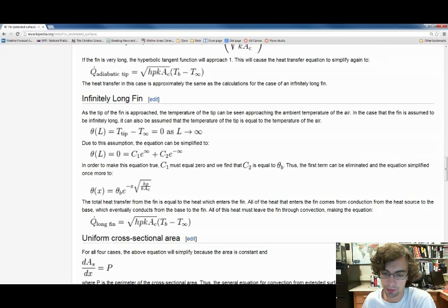It's a pretty broad range, and you can look at that in some of your heat transfer textbooks. But we don't have a very good prediction of what h can be. It can be a pretty wide range of values. So we don't know what this is, so we can't just plug and chug this into MATLAB or Excel and determine temperatures for all positions.